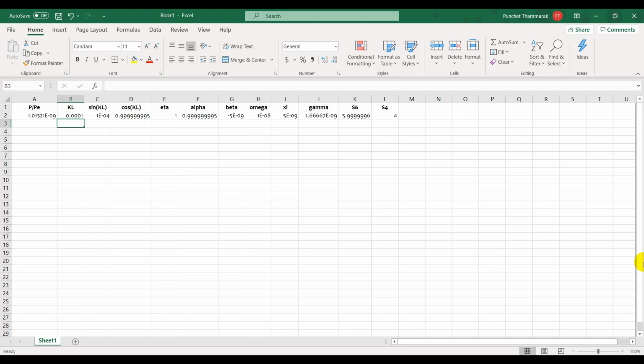If you compare with the geometric stiffness matrix, which is the simplified version, that one gives you a better result, because it doesn't have any sort of jumping of the function, divide by 0 or approaching infinity. So that is embedded as a part of the structural analysis program. Like I think SAP used the geometric stiffness matrix.